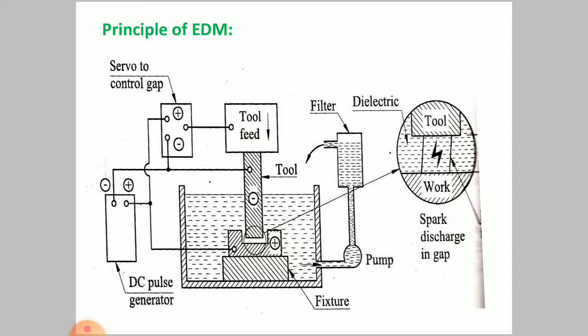That dielectric fluid will carry the dissociated ions, the dissociated atoms along with it, and an arrangement of pump and filter will clean the dielectric fluid.